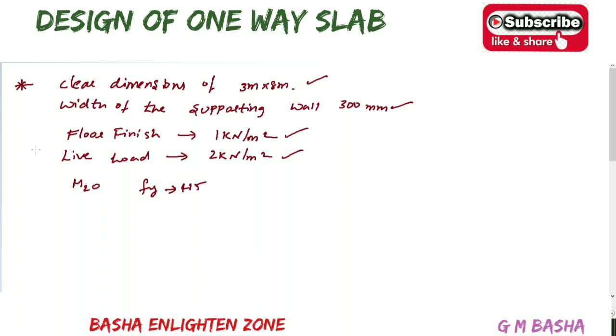So this is the data. Our first step is, here they mention a simply supported RCC slab, but they didn't mention whether it comes under the one-way slab or two-way slab. So first step is to find out whether it will be one-way slab or two-way slab. For that, take down the given data as it is. And the next step is to take the ratio Ly by Lx. The clear dimensions are given as 3 meters by 8 meters.